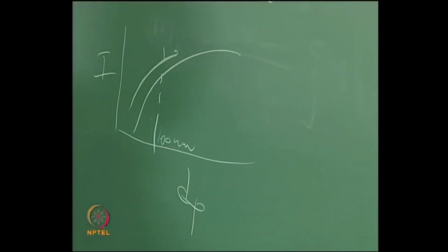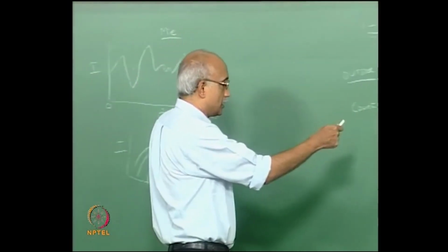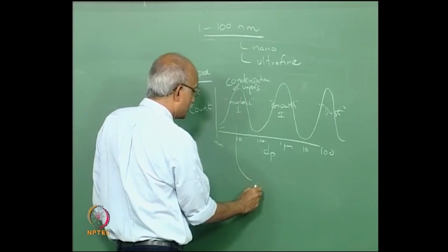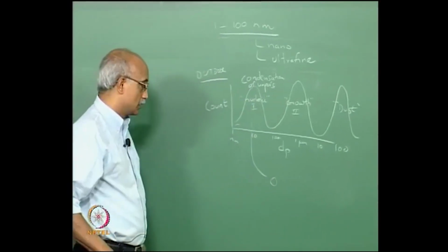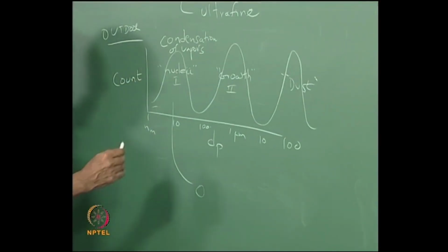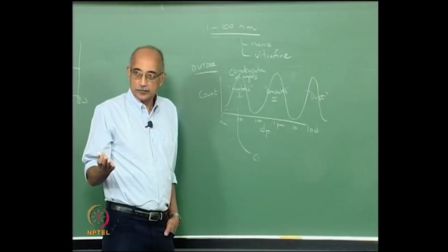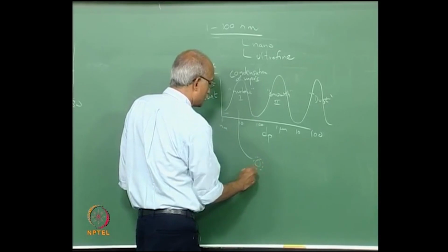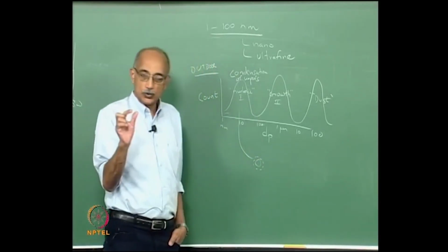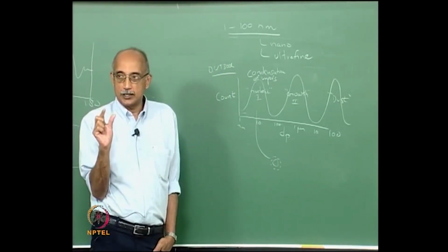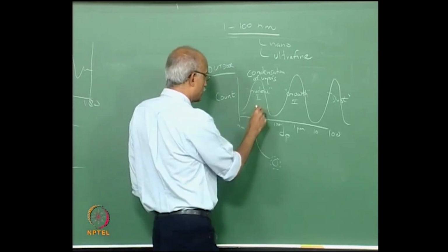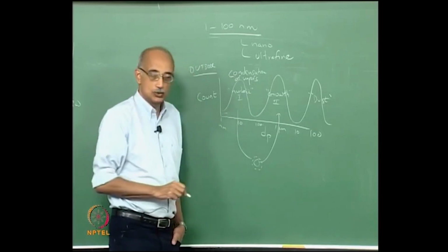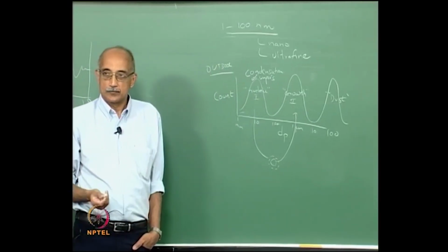Well, going back to these curves, essentially what we try to do, if you are trying to measure the size of a particle in this size range, is introduce a vapor which condenses on top of this particle and grows a sufficiently thick layer so that this particle size is migrated from this range to a more measurable range.